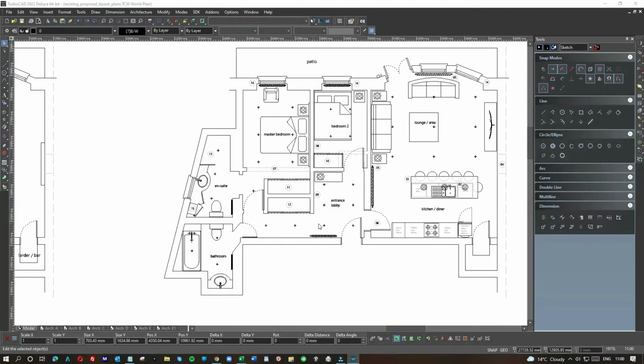As you can see, it was designed, we could have pulled it forward here, we could have put the wall here, more wardrobes, more space for the bedroom, but also at additional cost because this is a structural wall. So we went for structural here, we had no option. We took that out at good expense, plus, as I say, a few structural bits of steel had to go in. Here we minimized the cost by leaving it there. Didn't feel that by pulling it out and gaining a metre to the bedroom and less for the hallway that it was going to do anything for the bedroom. Where the bedroom lacked was in the width rather than the depth, so it was left.